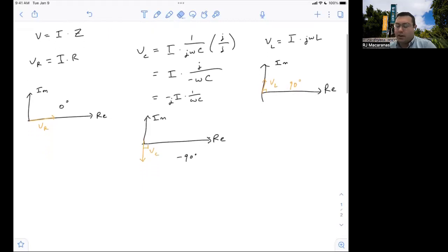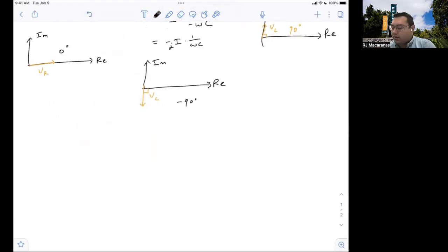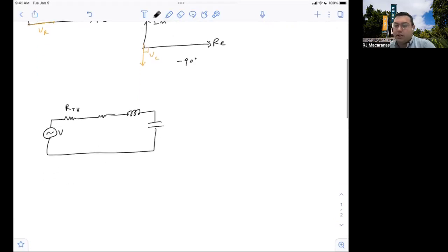Once we have this impedance model in mind, we can take a look at one of the circuits that we've been analyzing and make sense of the response that we observed in lab. So let's take a look at this RLC branch. And I'm going to also introduce the source resistance. We found in lab a number of times that these power supplies and function generators that we are using actually have some internal resistance. So we'll model that by some R Thevenin, and this has some V Thevenin, because by Thevenin, we can reduce any network into a voltage source in series with this resistor.